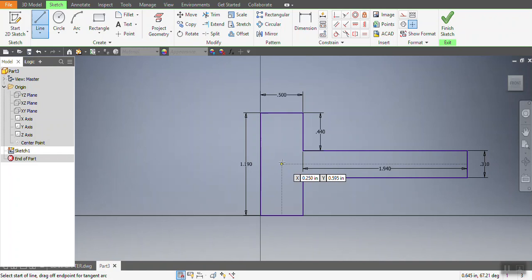of the circle. So I'm moving my cursor somewhere approximately in the middle of the shape, and knowing that the computer will see the center point of the utmost right vertical line and the center point of the utmost lower line, bottom horizontal line, and it will show me dotted lines in between, an intersection of dotted lines, showing me that there is a perfect point, the intersection of these two midpoints. And it shows me with the yellow mark. So I click on it. Okay, this is the center point.